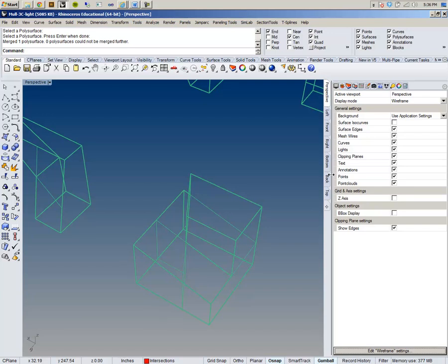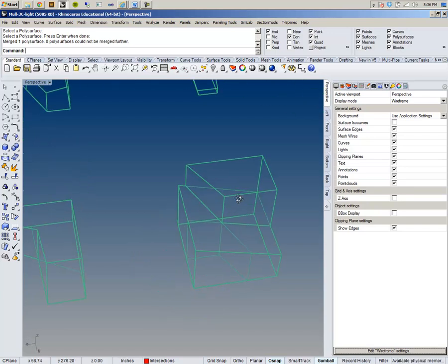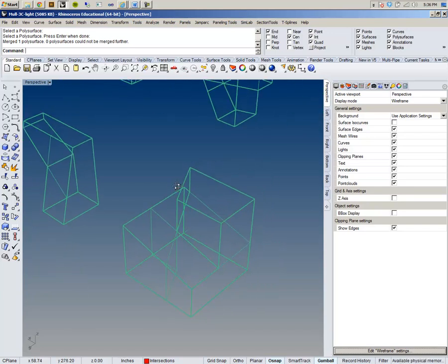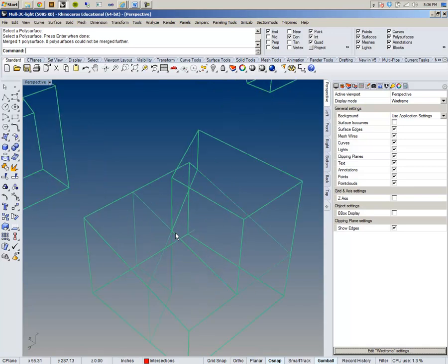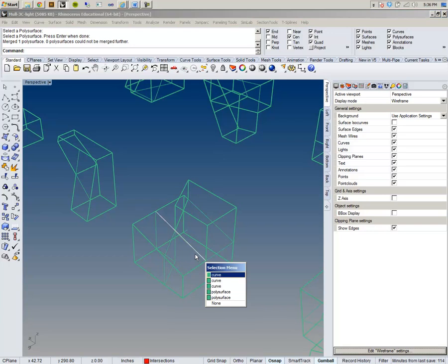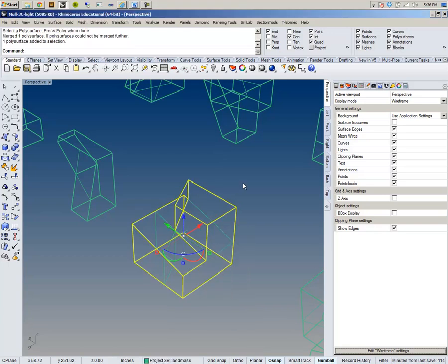When you put the nesting model in the middle of that, could you do a Boolean split? You create a pocket for the model, or should you just leave it at that? No, yeah, you still do that part. This gets us to where you would still do the split and get it out of there. You can do a difference too, because the split is going to give you that third thing, which is the intersection of the two, which is fine. You just have to remember to delete it. So the Boolean split works too.